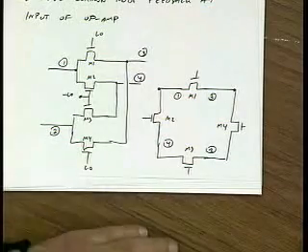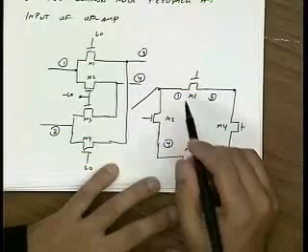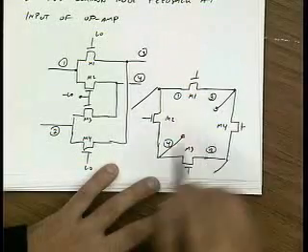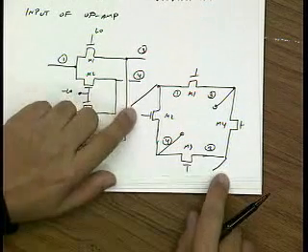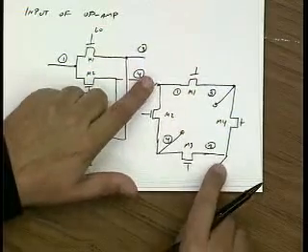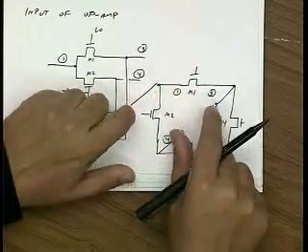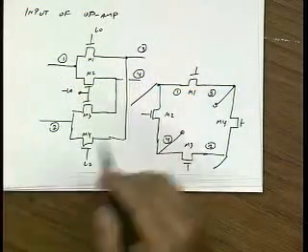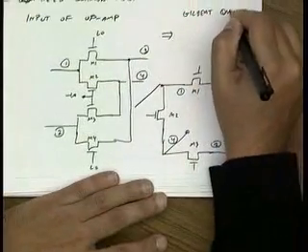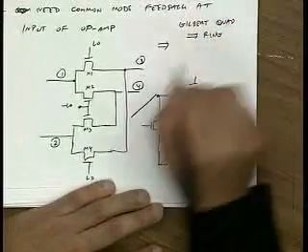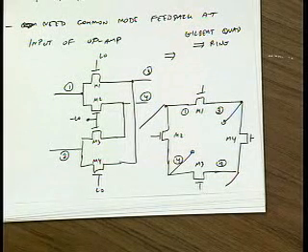So really, this is a ring. I bring in my input from one side, and I take my output from the other side. Basically, the first thing we looked at was I could voltage drive this ring, and this would be my output. Now we're current driving this ring. I'm injecting a current and taking a load current at the output. So really, the Gilbert quad is the same as a ring. Okay. Questions?